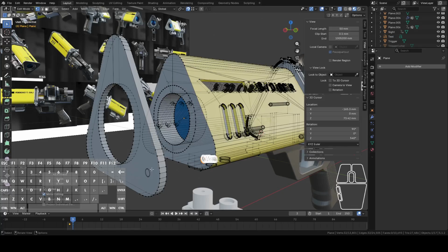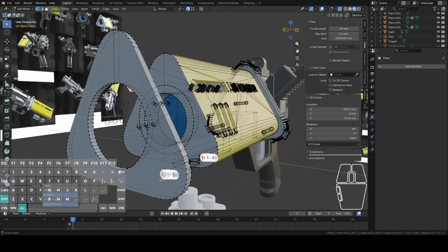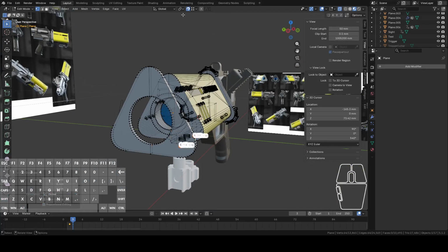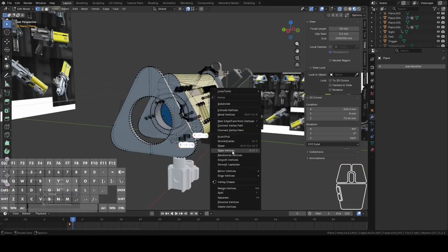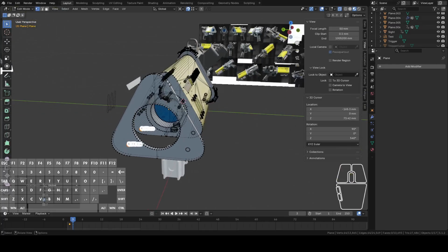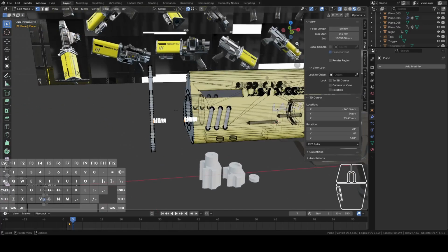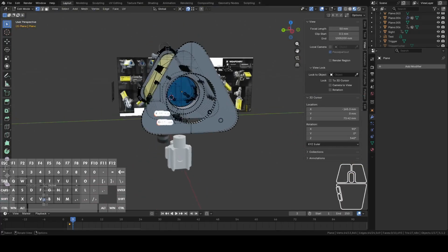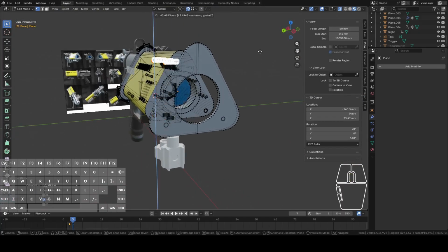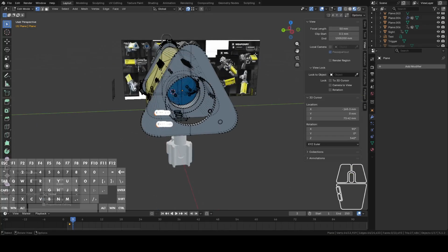And I wonder if I should do one on both sides, and one in the center, or just the two on the bottom. While we're here, I figured we might as well do both. So let's Shift D over here with 3D cursor as our pivot point. We'll right click, and then where's mirror vertices over the Y axis. And you can tell using these guys, the Y is going that way and the X is going that way, just in case you're wondering. And let's go ahead and Shift D again and drag this up here.